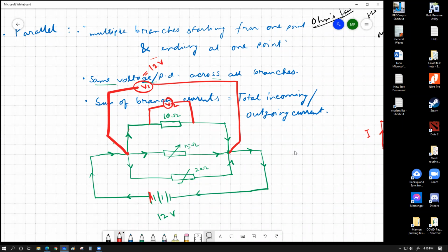Do you see any electrical difference between the connection points of voltmeter 1 and 2? Try to understand this very minutely, because this can be a point of confusion. What I want you to see is, from here through here, do you have any electrical difference? Are these 2 points electrically equivalent or not? Yes. Similarly, these 2 points are also electrically equivalent.